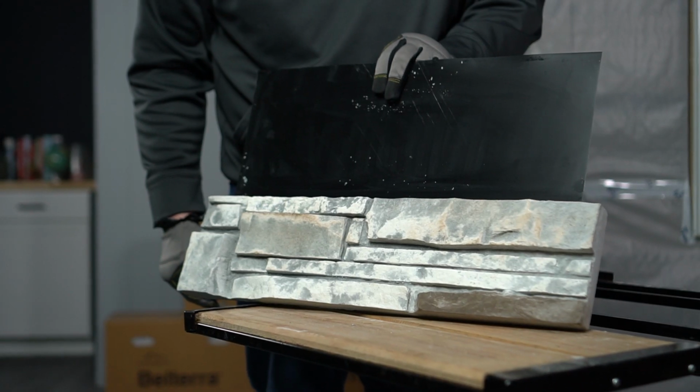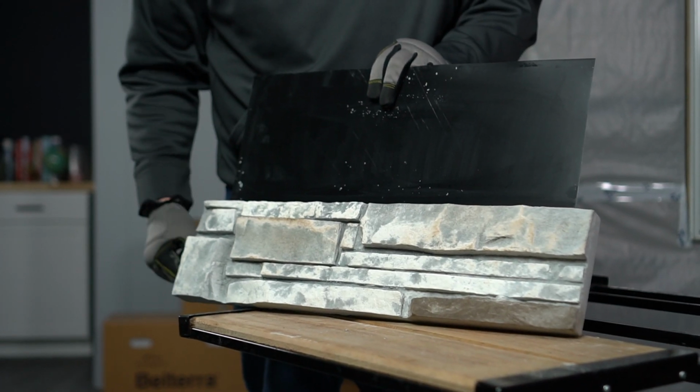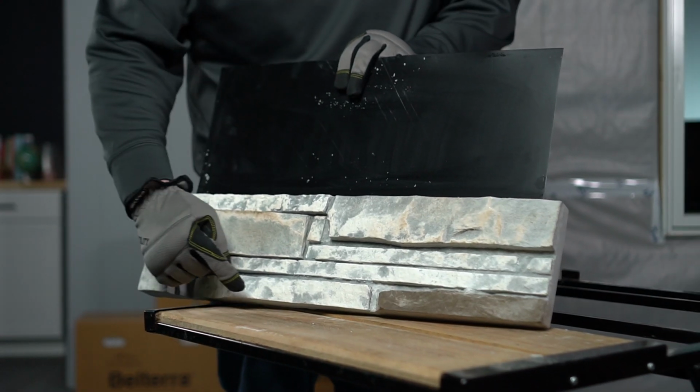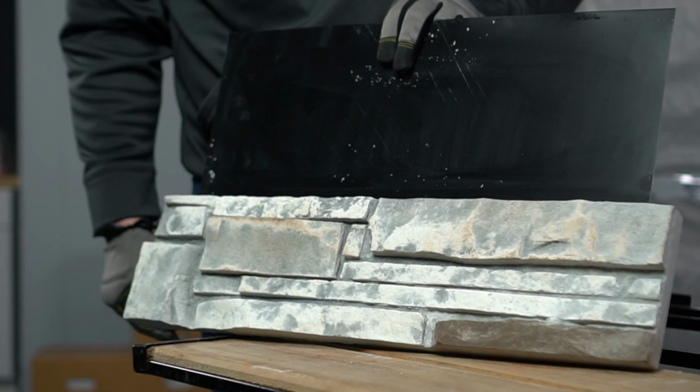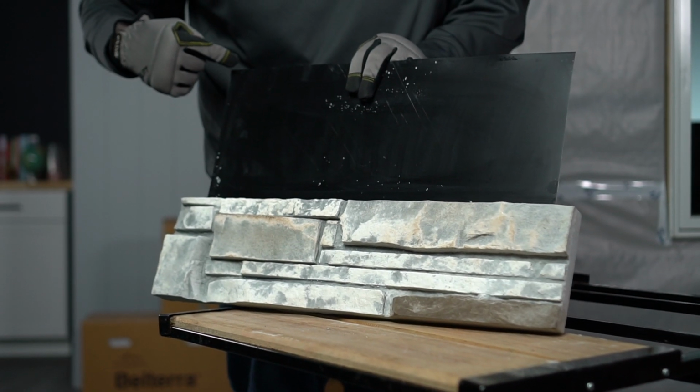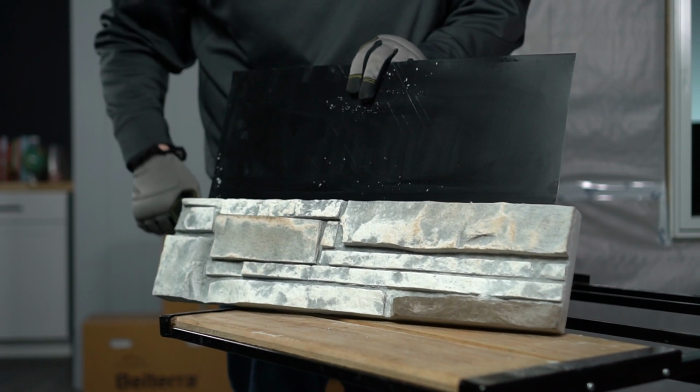The core component of the Silvermine Stone system is the flat panel. Each flat panel measures 6 inches tall and 24 inches wide and provides 1 square foot of coverage. You will also notice that the panel has a piece of coated metal flashing that is embedded into the panel during the casting process. This metal panel serves to attach the panel to the wall while also creating a shingling system that keeps moisture away from the wall.